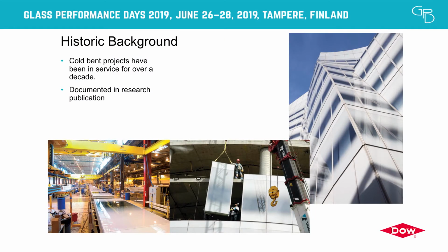So the idea behind this research is trying to develop a more holistic method of data for use in FE applications for cold bent glazing. So just a quick operational definition, though I know most of you are aware. Cold bent glazing is the application of taking a perfectly nice and flat curtain wall, and when in construction on the building, you actually bend it into place. So you're putting a tension load on it, a permanent load, in lieu of a hot bend application.